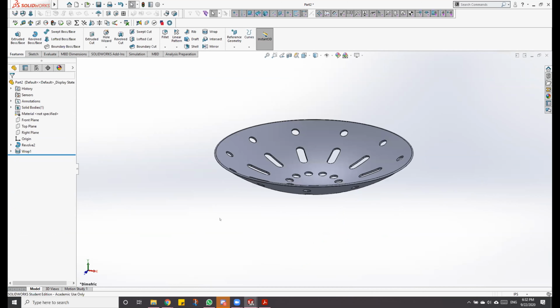Did everybody's work? I hope they did. If it doesn't work, you can also just do an extrude cut on the sketch, even though it's not on the surface, it'll just go through the strainer anyways.